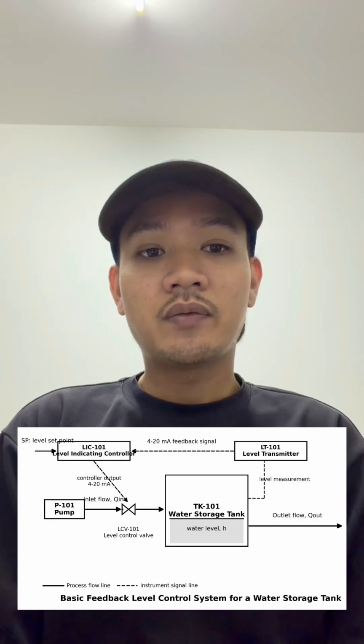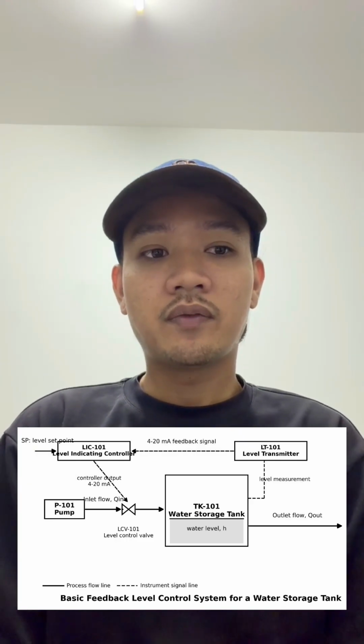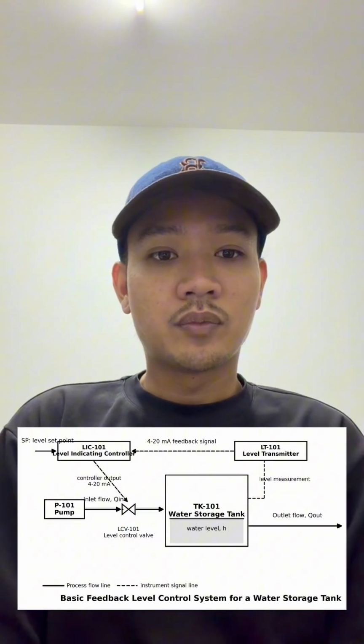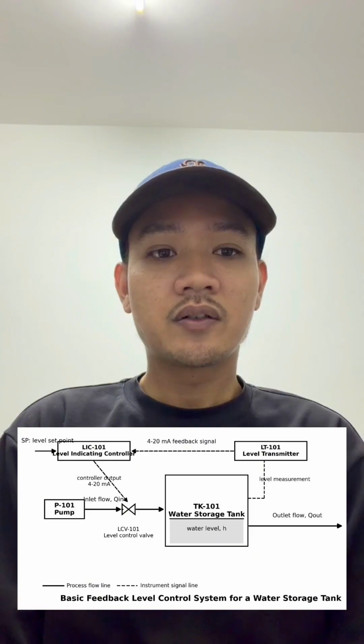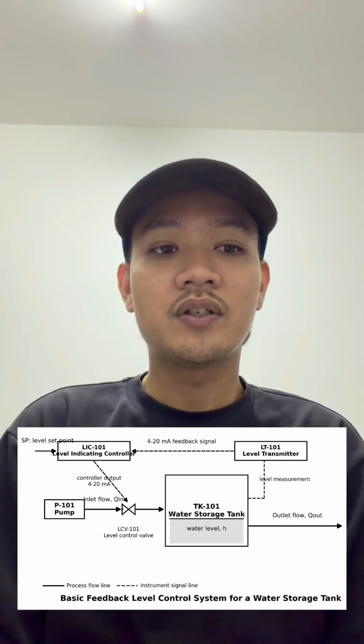If the water level is too low, the controller opens the valve to allow more water to enter the tank. If the water level is too high, the controller closes the valve to reduce the inlet flow. This is called a feedback control system because the system measures the tank level and uses the measurement to control